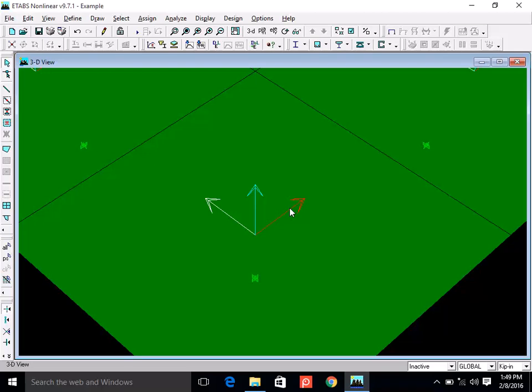So the bottom line is that in case of slabs, the bending moments are about in plane axis, either 1 or 2 or both of them at the same time. When you have a two-way behavior, then of course about both of them. And shear is about which axis? It's about vertical. It's along vertical axis because we have mostly gravity, right?